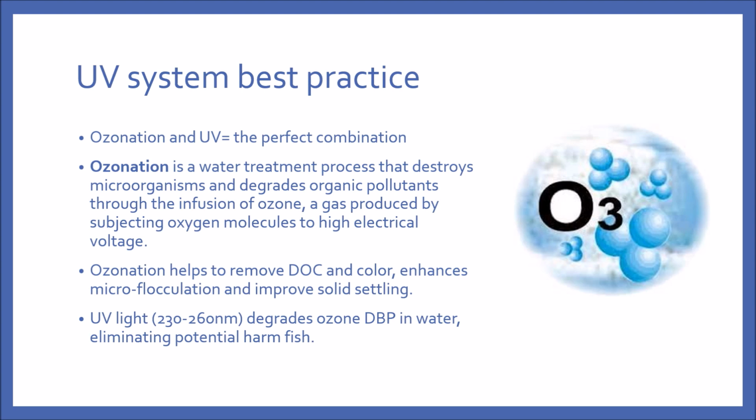In our plant, we are only utilizing a UV light, and the UV light we are using is about 90 watts. We have to proactively replace the UV light every 8 months. In some water treatment processes, it is common to include additional filtration steps such as microfiltration or ultrafiltration prior to the UV plant, or in our case, we are utilizing what we call a protein skimmer to remove any fine solids before it is introduced into the UV system to ensure that our UV is at its peak performance.